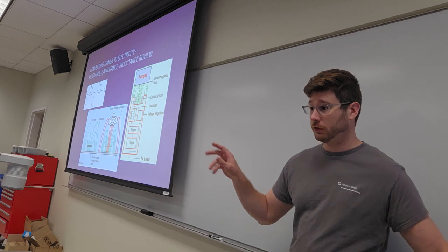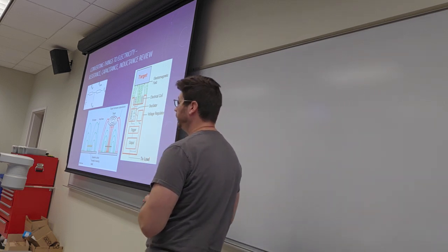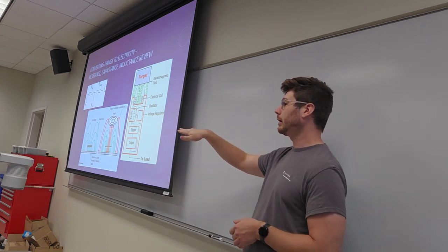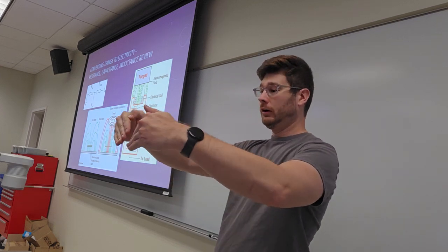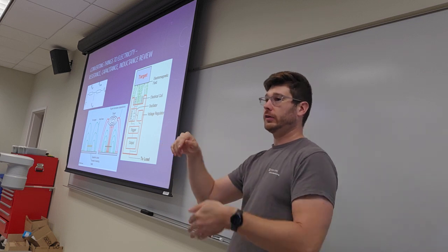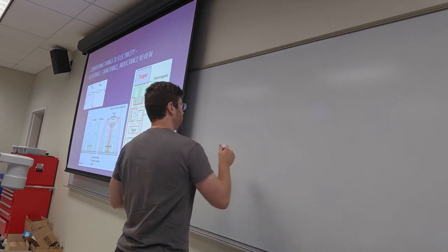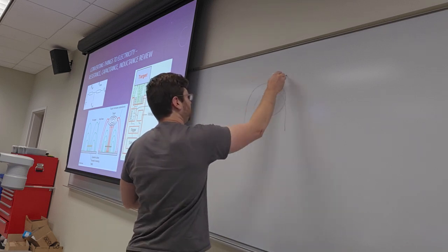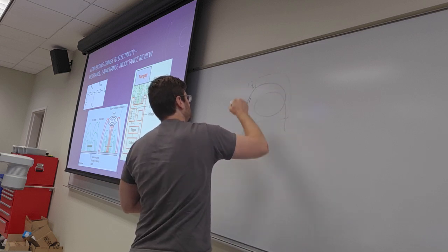Okay, so one thing that we didn't go into last time is inductive sensors. My favorite example of an inductive sensor is the type that recognizes your car is rolling up to a stoplight. People may or may not know this, but you see that almost like a chunk is cut into the ground right before you roll up to that sign. What's actually embedded in the ground is a very large coil, literally, run underneath the cement pad, and there's always some current running through it, right?